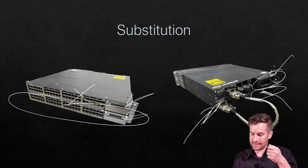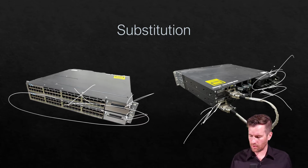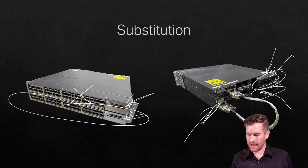And then if it's still not working, then we realize it's not the power cord, because those are known good power cords. So now we suspect that maybe it's these power supplies. Well, these power supplies happen to slide out, so we could slide those out and take the one from the known good switch that we know is operating, slide them in, and then test that out.